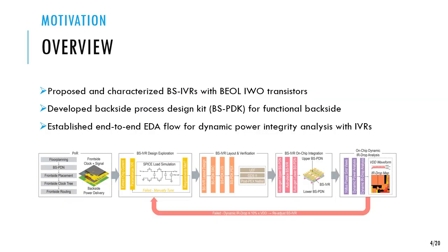Our contributions can be broken down into three folds. We first propose and characterize backside IVRs with the novel back-end-of-line tungsten-doped indium oxide transistors. Secondly, we developed our process design kit to characterize these back-end-of-line transistors and to fully design and verify our backside IVRs rigorously based on a commercial technology node.